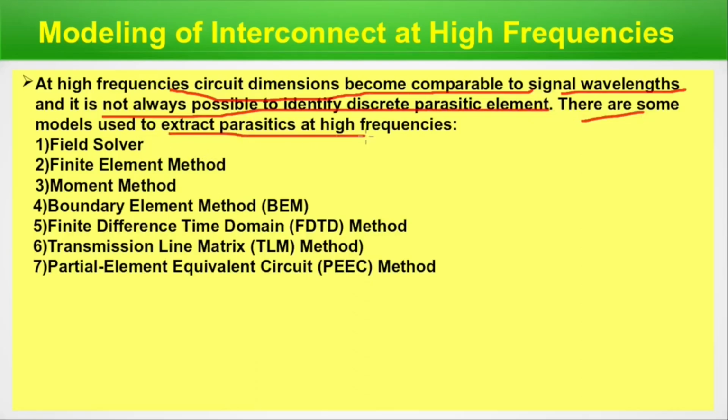Field solver, we already mentioned it. Actually, a field solver solves Maxwell's equations using the finite element method, moment method, boundary element method, finite difference time domain method, transmission line matrix, or partial element equivalent circuit, the PEEC method. These all are used. We already mentioned the PEEC method. So these are standard methods used to solve this, and the EDA tools use different models inside them. These are basically the models used to solve the equations and to get the parasitics at high frequencies.